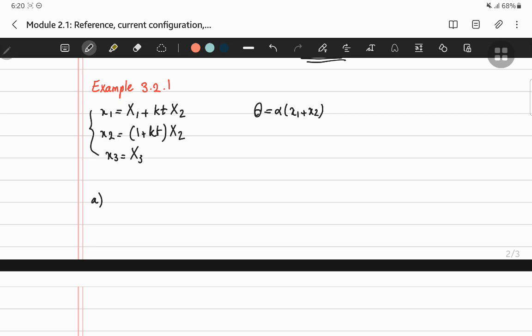And the material description, as you see here, this is the spatial description of the temperature field. So it is like theta tilde. So if you want to find theta hat of it, we have to convert this spatial description into a material description or Lagrangian point of view. And the book actually didn't put this tilde here because it already uses small letters x1 and x2. So you know that you are in spatial coordinate or description.